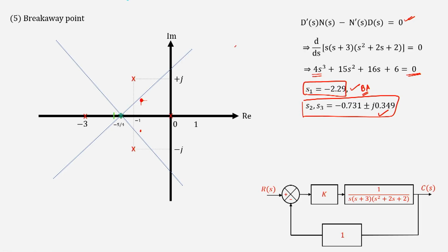Now, for a point to lie on the root locus, it must satisfy this equation, right. This is the characteristic equation, which is actually equivalent to, as I have time and again said, the magnitude criteria and the angle criteria. So, it has to satisfy both these criteria. We will just check the angle criteria because that is the important one, since not all points satisfy that criteria. Now, at this point you have to check whether this satisfies the angle criteria.